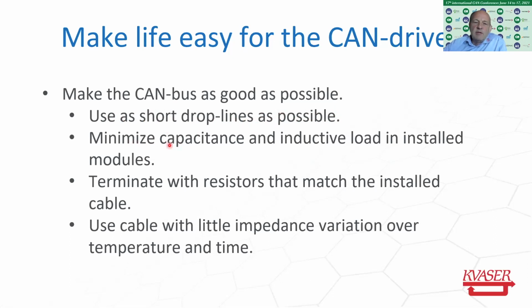Another time, you put a lot of capacitors and inductive loads in the ECUs for EMC reasons, but those passive components that store energy can make it complicated to analyze and understand where the energy comes and goes. So if you get away without the capacitance and inductive load in the ECUs, it will be easier to understand the behavior of the CAN bus.